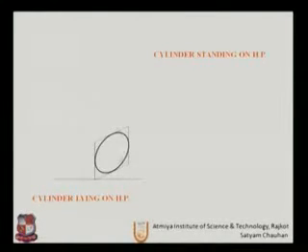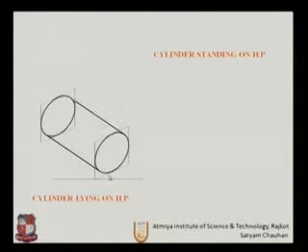So that will be the base of a cylinder, and then with the given height, let us draw the similar view, producing the same view with that length in isometric. So the line will be 30 degrees again, that line will also be 30 degrees, and simply join, and we can rub this part in order to show the 3D.